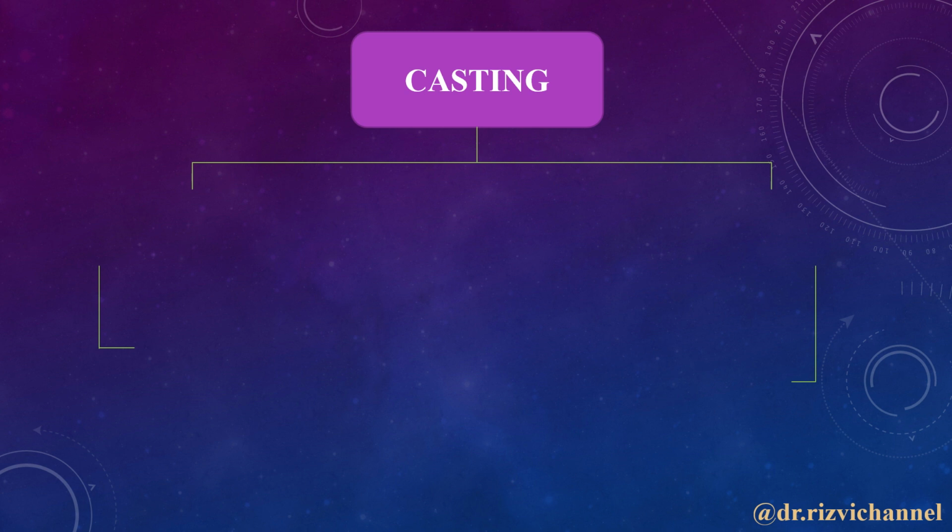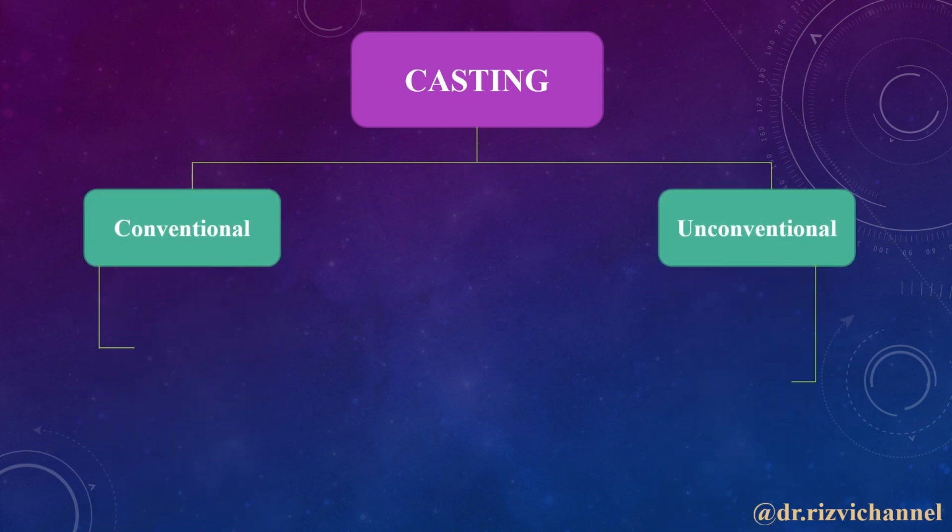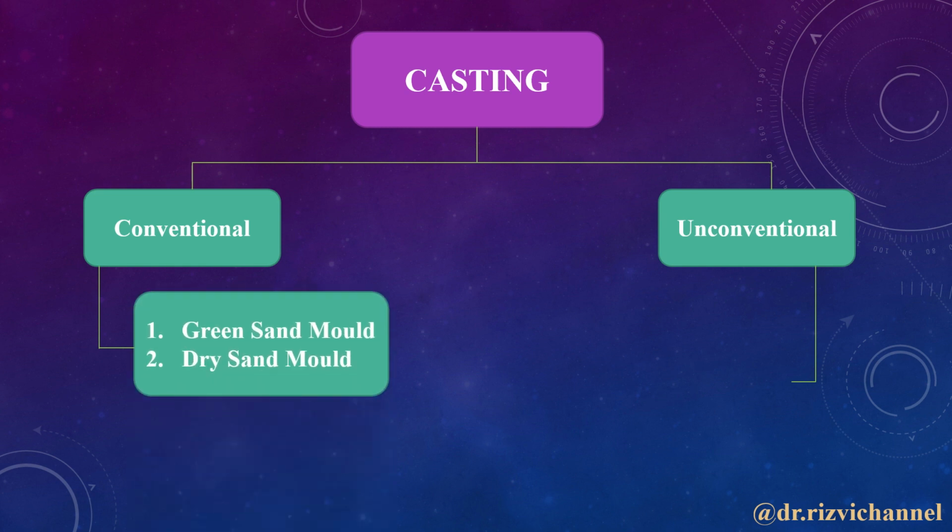The casting can be classified into two types. It is conventional or it is unconventional. There are two types of conventional casting processes. They are green sand mold and dry sand mold. When the sand used contains moisture, it is known as green sand, and when it is used in dry format, it is known as dry sand mold.